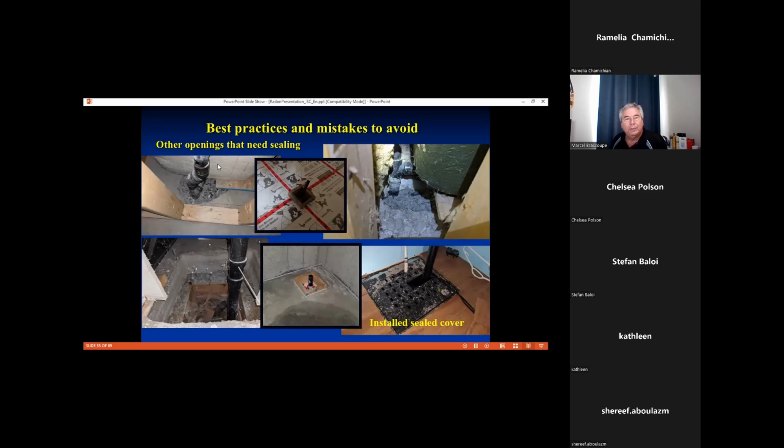Underneath the bathtubs, this is typically what we're seeing. You'll see on the left here, crushed stone, nice big hole underneath the bathtub. In new construction, they put a box, nice big hole. Underneath the shower here, you can see the crushed stone, nice big hole. These are big holes. These are probably about 16 by 16 holes. So typically that's just left there. After the plumber is finished installing his P-trap, that's just left like that. So again, there's a lot of radon coming through that home. Remember, it's being sucked in with this stack effect.